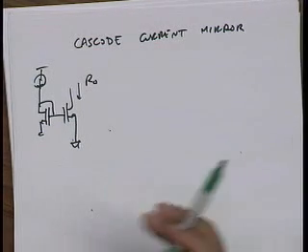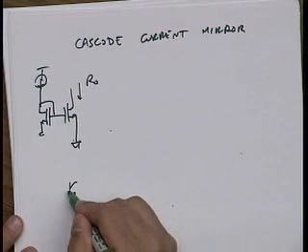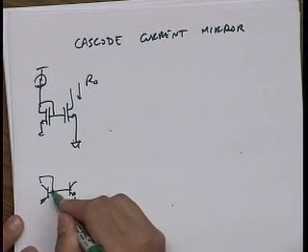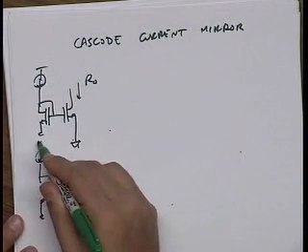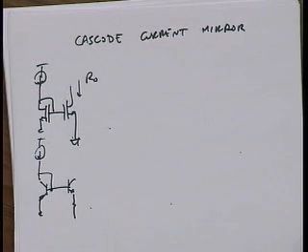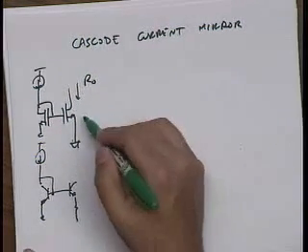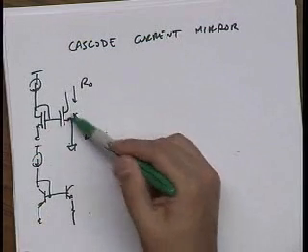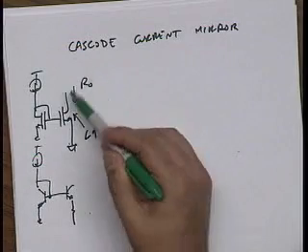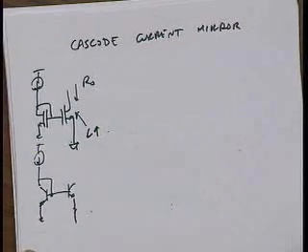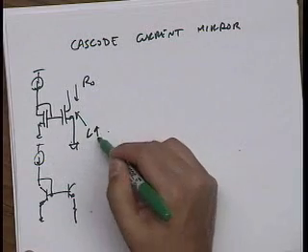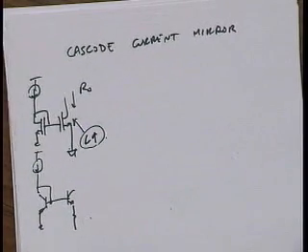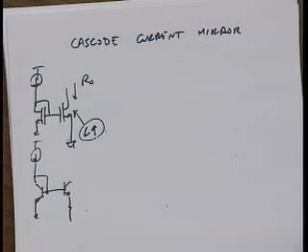Okay, degenerate it. In bipolar, that's a good choice. In MOS devices, there's almost no point to degenerating, because I can achieve the same effect by doing what? Just use a longer channel length device, right? I know the output impedance of this device goes up with channel length, so I can increase R out by playing around with the W and L of this device, and certainly I want to use the largest L I can get away with because that's going to give me the highest output impedance.